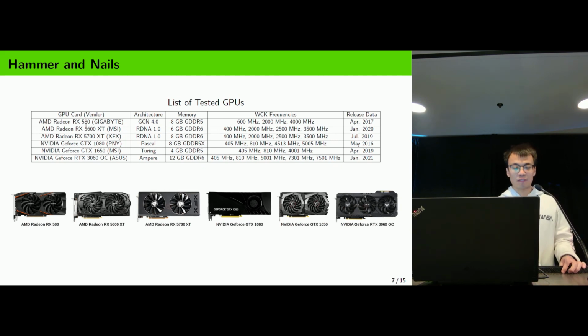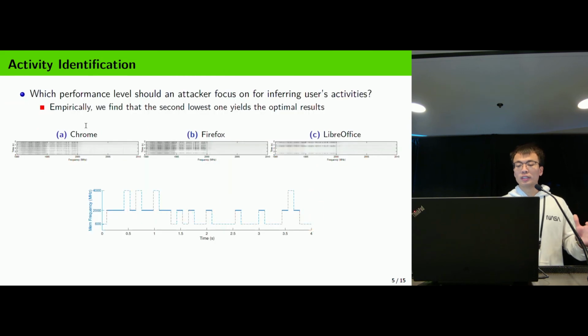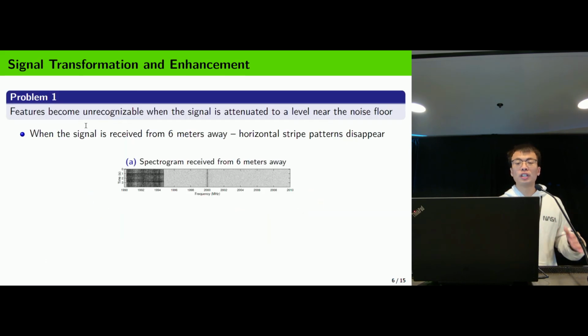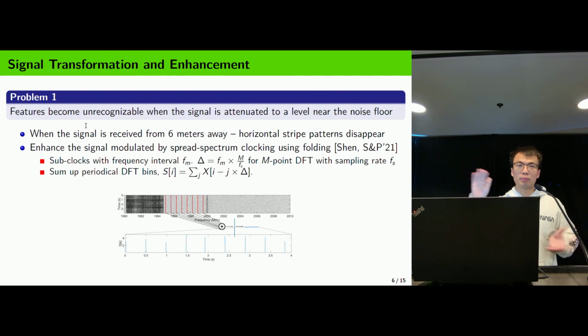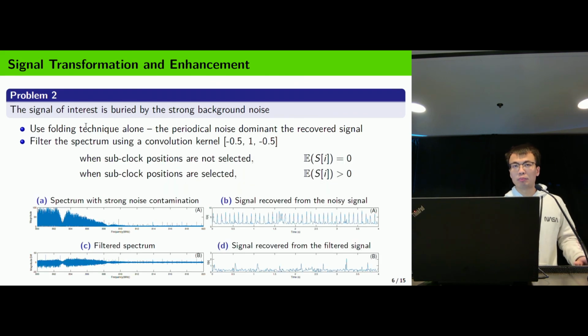So for defenses, you proposed the Faraday cage, and then you said maybe it wasn't that effective because you tested with metal-cased GPUs. Am I understanding that correctly? Was that the metal case of the GPU, or the case of the PC the GPU is in? Actually, that's the case of the PC. Basically, we evaluated measuring the distance with 2 different types of cases. One type of case is completely metal, and even in that case, we can measure some strong EM leakages at some distance away.